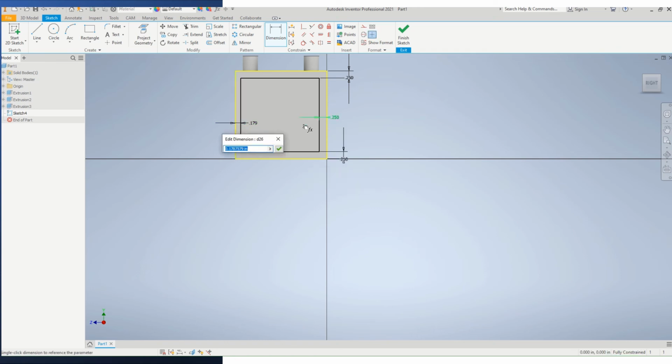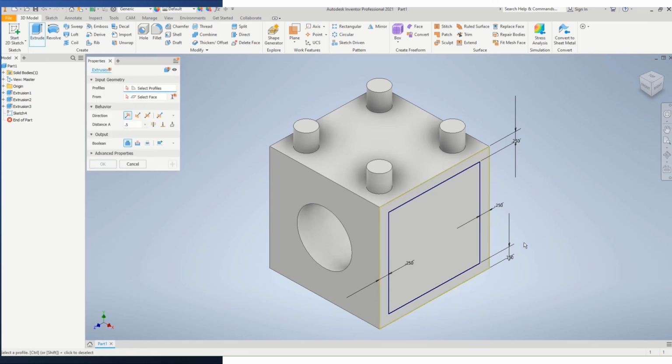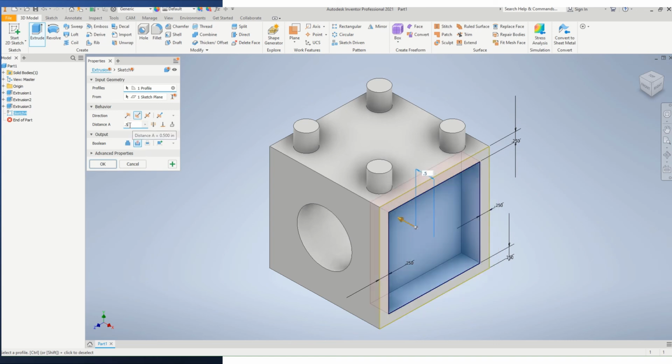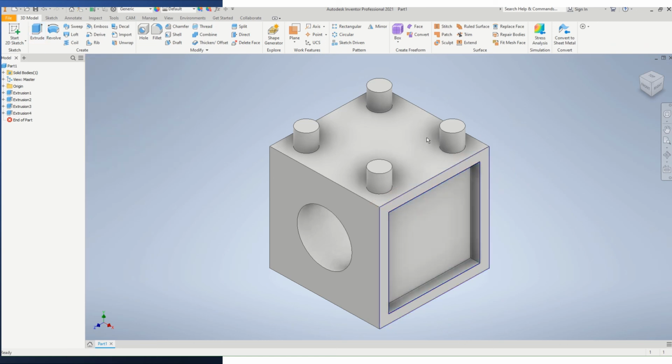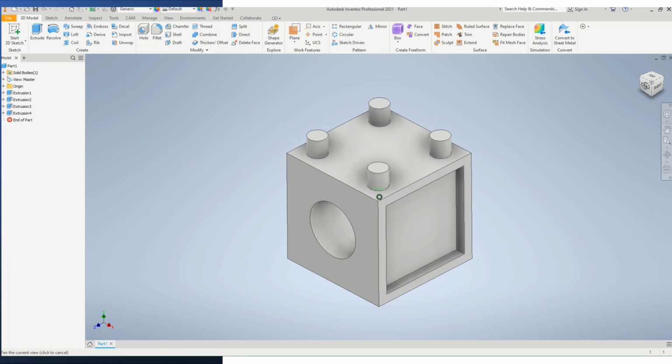And what I like to call this is an inlay. So we have the exterior of the picture frame, and then we have this rectangle on the inside. So let's finish this sketch. Now we're going to go to extrude. We're going to highlight the inside, but we don't want it to come out. We want it to go in, and we just talked about that. So we want to do cut, and let's go in 0.25, so 1/4 of an inch. So what we created is a happy little picture frame, if you could see this.